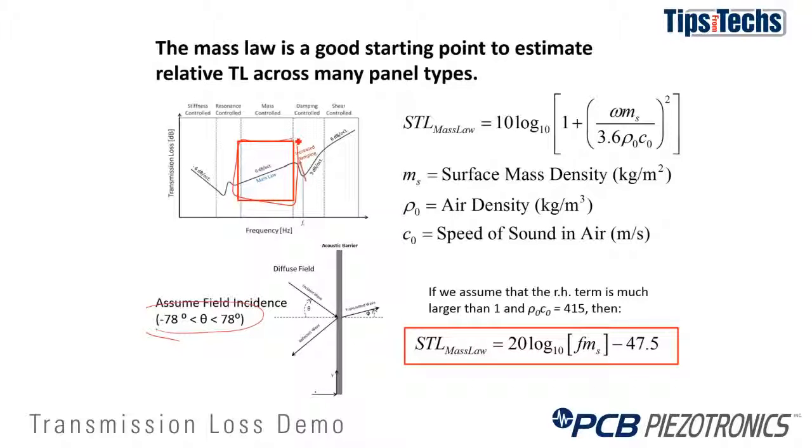Our mass law is shown on the top of this slide, and after we simplify for standard atmospheric conditions, it becomes very simple. All you need to know is the surface mass density and the frequency of the incident sound.